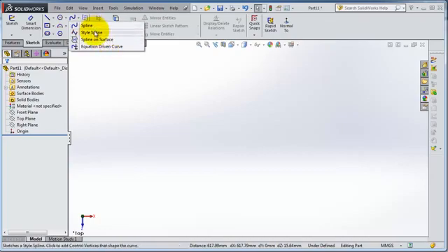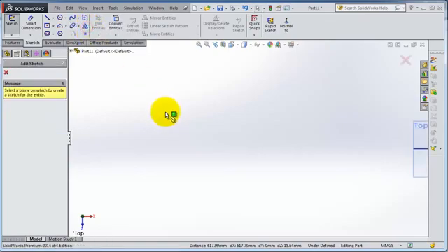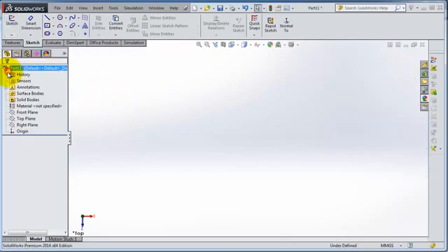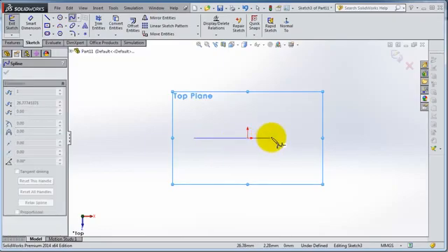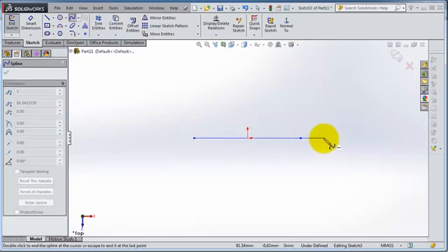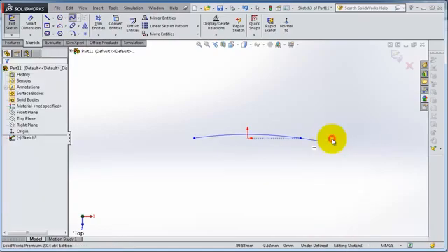And now we have 2 splines. The first one is this, and the second style of spline has points and edges to control the spline shape. So let's first choose the first type, the simple spline, and select a sketch. Spline. Now if you create a spline with 2 points only, and then we are done, right click, select or escape.